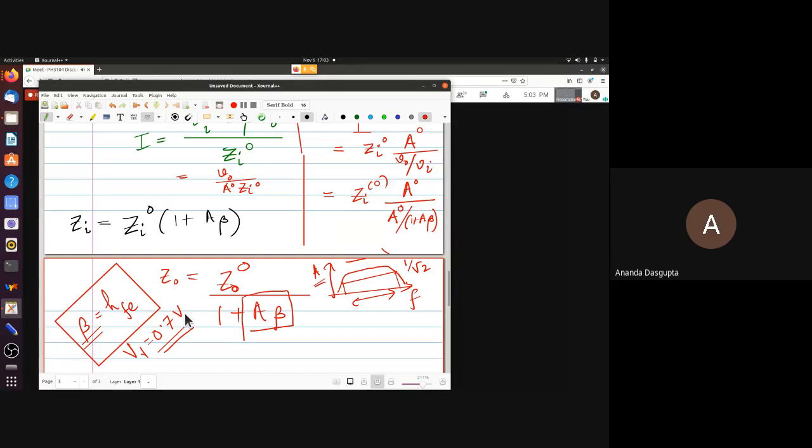That's actually part of the design, right? Emitter bias feedback is negative feedback, and that's why it stabilizes against variations in beta and so on. We did not use the negative feedback language so much there. I did explain why it works as part of the video, but maybe I did not use this language. But you can easily see it as negative feedback, which tries to bring down the input. When you have a resistor on the emitter side, any change in the current makes the voltage drop across it larger. That makes the emitter go higher, and that makes the base-emitter voltage, which is the actual voltage that controls all the currents, come down. So the input goes down with the rising output. That's what negative feedback is, and that is why the emitter feedback resistor stabilizes.